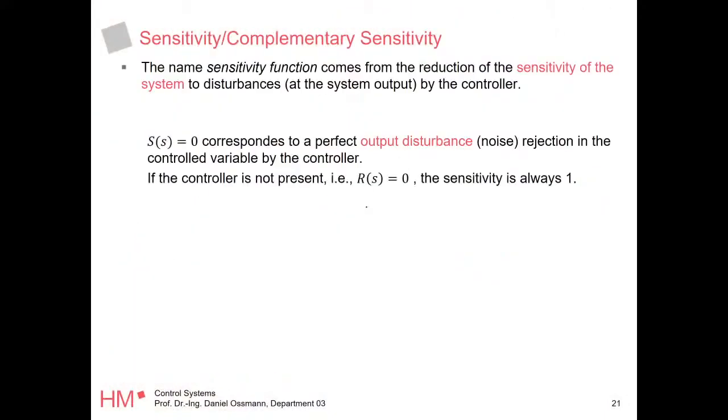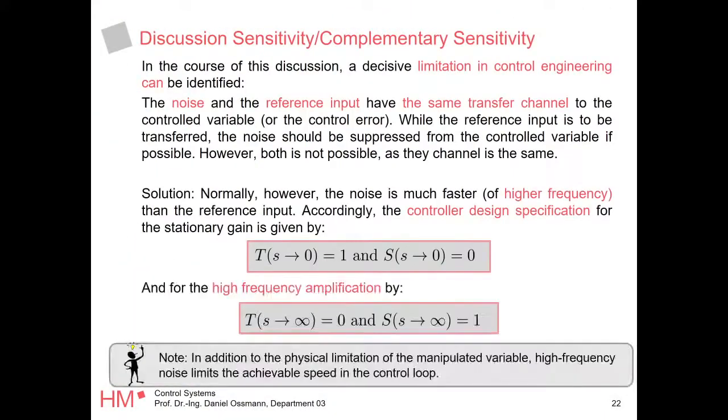Now I'm mainly talking about transfer functions, but if you want to know how an impulse, a step, a ramp is acting in that control loop, you take the transfer function from that closed loop and you still compute the final value or initial value theorem the same as before. Hope that's clear. Actually, let me see. Yeah, this is actually in the example we're going to do after the next 5 slides. You should see that then. Okay, this is where we are.